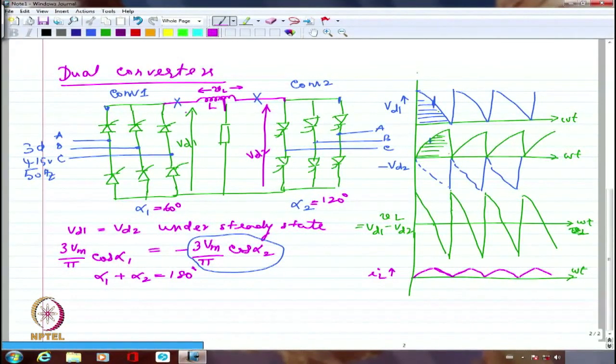Of course there will be a load current. Maybe there is a huge amount of load current being drawn. The load current drawn is being supplied by the rectifier, and it will also pass through at least part of the inductance, no doubt about that. But if the load current becomes almost like a steady current, it is not going to contribute to the inductance stored energy, because only L dI by dt contributes towards the inductance stored energy.